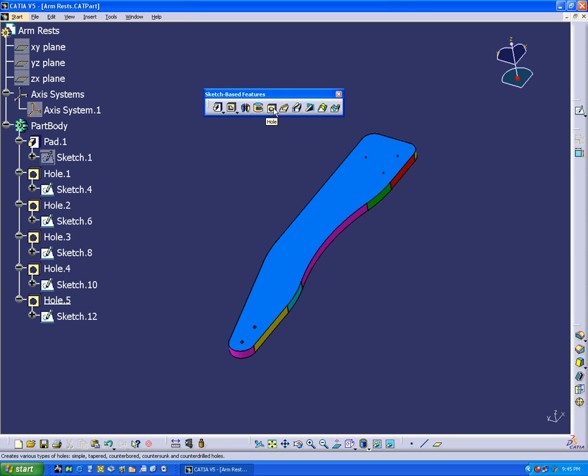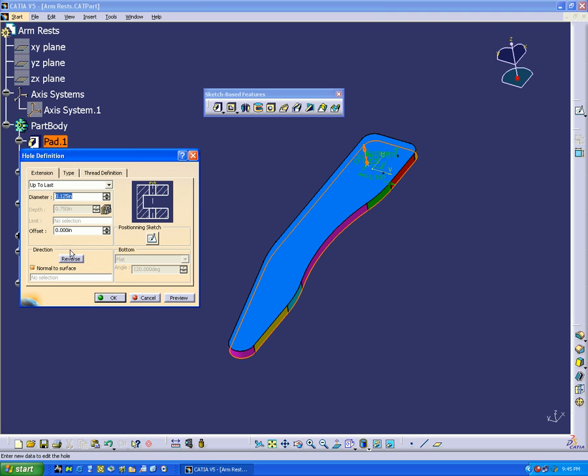Here's something that you can make a hole of. For example, this hole right here is made with that hole function, and I can click on it, and that hole is a 0.125 diameter pilot hole for a deck screw fastener, and that hole can be very quickly made with the hole function. I'll cancel out of that.